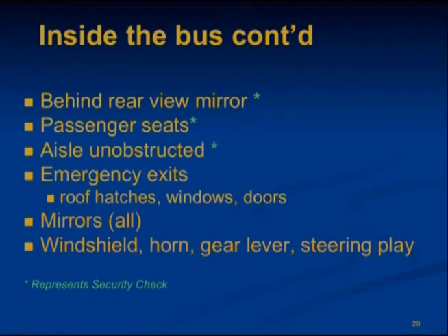Check your windshield to make sure that it's clear and clean inside and outside. It is essential that the driver's vision is not impaired by dirt or film on the glass. Never place decorations or anything else on any emergency window, door, or the windshield. There should not be any illegal stickers, even if they are transparent.